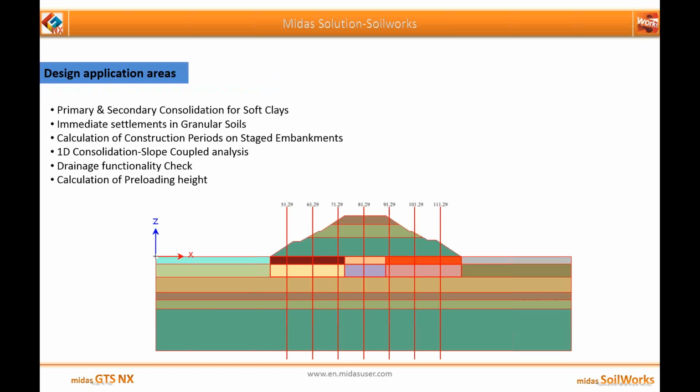So the design application areas: the primary and secondary consolidation for soft clay, immediate settlement in granular soil, calculation of the construction period on stage embankments, 1D consolidation slope coupled analysis, drainage functionality check, and calculation of the preloading height. Now what I will do is move on to the program to solve an example in 1D consolidation analysis, so as to make you familiar with the general workflow in MIDAS SoilWorks.